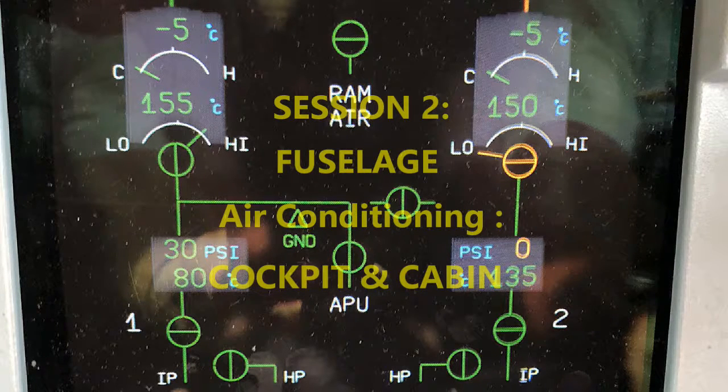The mixing chamber I mentioned a bit ago is made up of a laminate with a metal flange bonded to the top. Then you have a distribution head made out of aluminum that is connected to that same flange, and that's distributing that mixed air to the system supply ducts. It's going to contain the hot air that's supplying the different cabin zones, your forward and aft cabin.